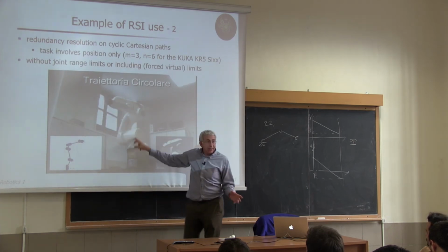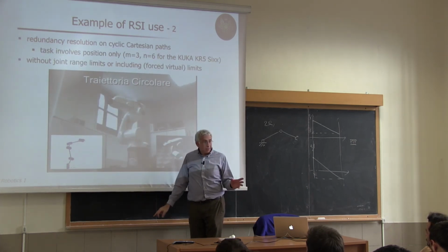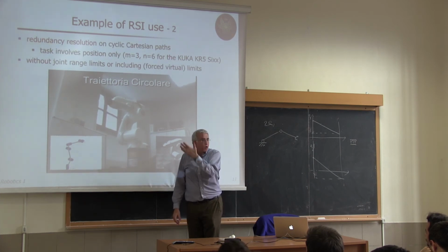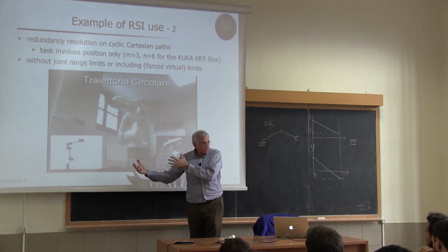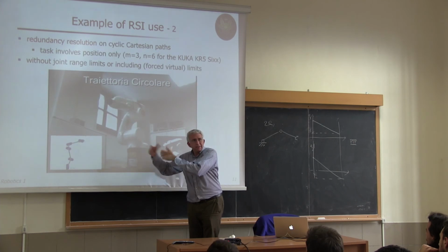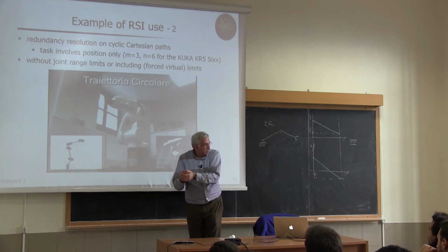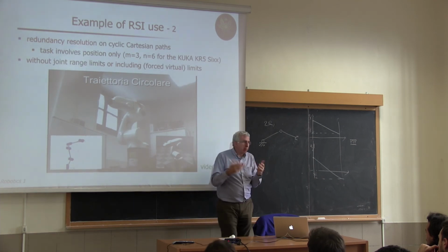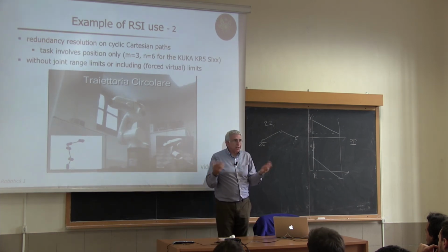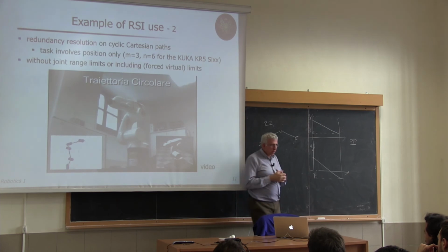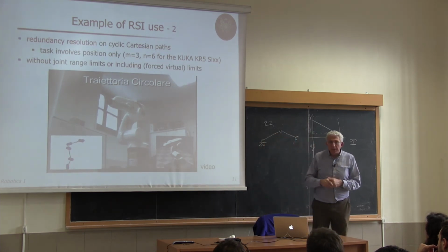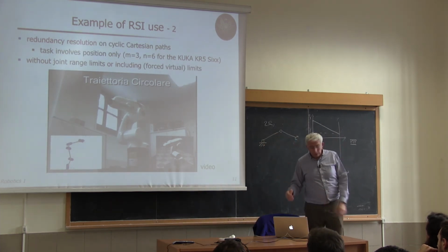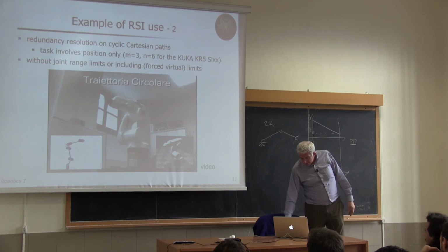Since the robot has 6 joints, we will work here with a Jacobian which is 3 by 6. So we are in a case, if we want to solve an inverse kinematic problem, where we cannot use, for instance, the Newton method as such. So inverting a non-square Jacobian, we should use the pseudo-inverse, or the Jacobian transpose if we use the gradient method. So this is how it works.